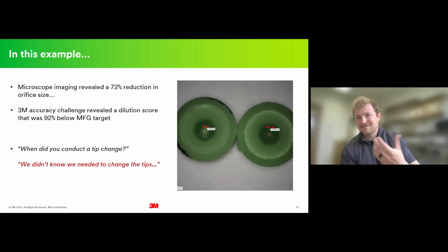With chemical management, chemicals are being forced through those dilution tips. When the dispenser is in the off position, the water evaporates from that tip, but the chemical that was in that tip is still there. So the chemical sits, the water goes away, and the chemical may still be sitting in that tip. As that same situation keeps happening, it compounds over time and the tip size gets smaller. So I would encourage you to routinely inspect, in a cadence that works with your procedures, and to connect with the manufacturer of your unit to figure out the right procedure. But you definitely need to inspect or replace these tips.